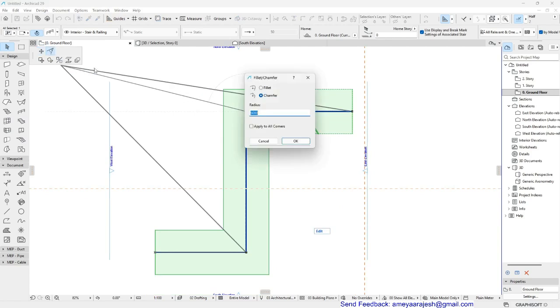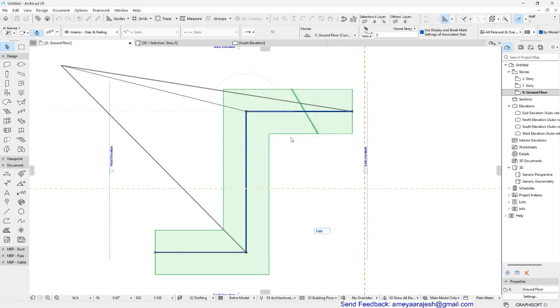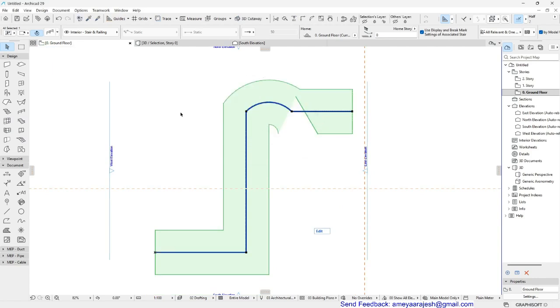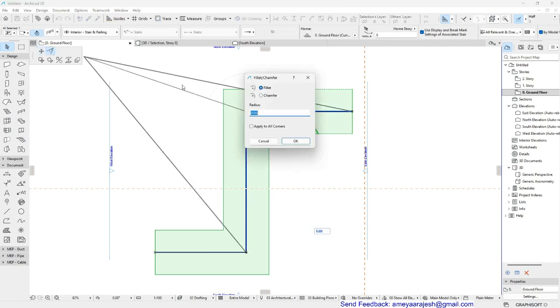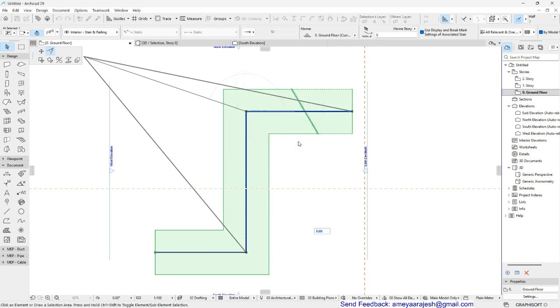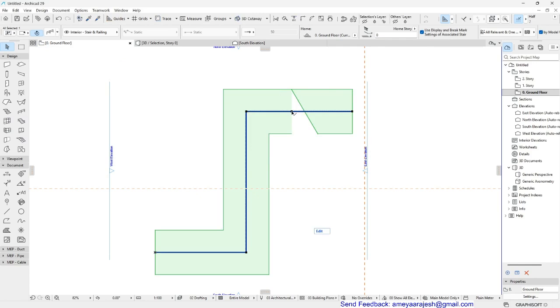What will happen now if you use the fillet option with some proper radius and say okay? You'll get a wrong result. So you don't do this. Instead of that, you can use a very simple option. Same fillet, but you go with the chamfer logic, leave the required distance, say okay, that is the radius value, say okay. You will see you will get one node out over here.